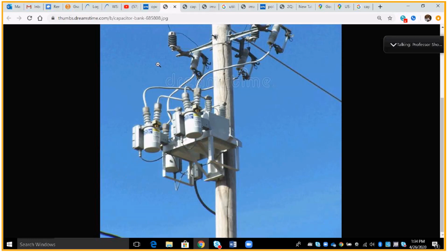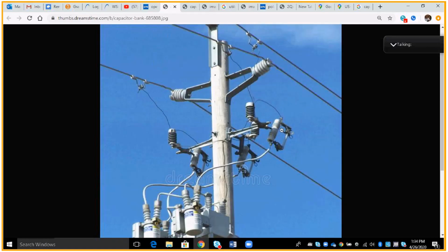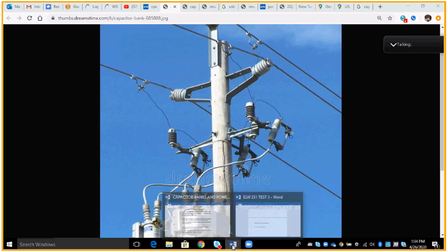But during the work, say they notice this switch is bad, or they got a bad fuse barrel or bad connection. Well, now I've got to get up into this area that I'm going to put my rubber goods and everything on, just like I would before. I'll take the riser off, but you are in hotline work permit area. Once you get above the bottoms of these switches, you are in hotline work permit areas. So obtain that hotline work permit if you need it.